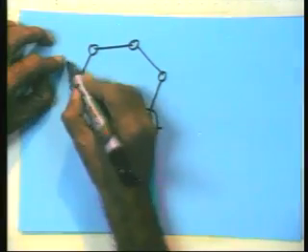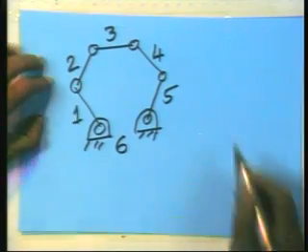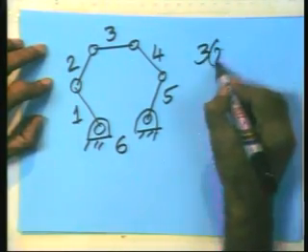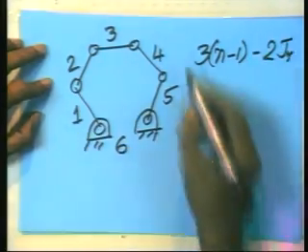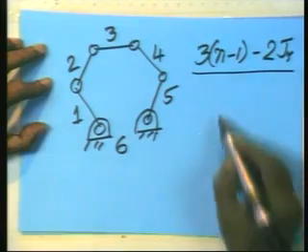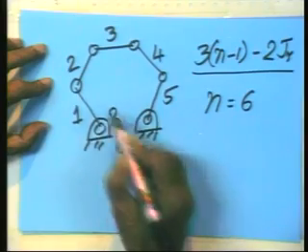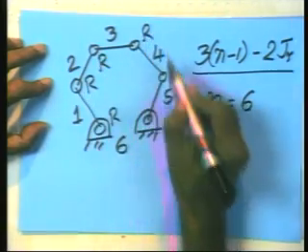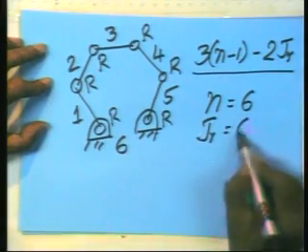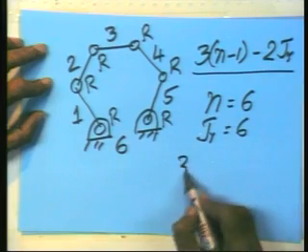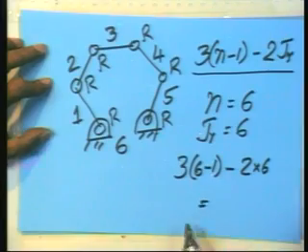So this is link 1, link 2, link 3, link 4, link 5. So let us write the formula. 3 into n minus 1 minus 2j revolute. We don't have any prismatic, so I leave it out. This is the degrees of freedom formula. N equals 6. How many revolute pairs are there? 1, 2, 3, 4, 5, 6. So JR equals 6. Am I right? Check. 3 into 6 minus 1 minus 2 into 6 equals...